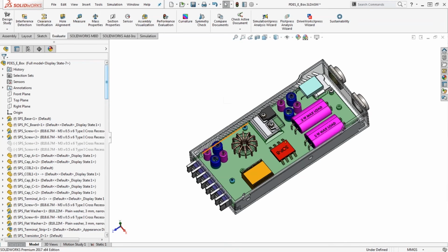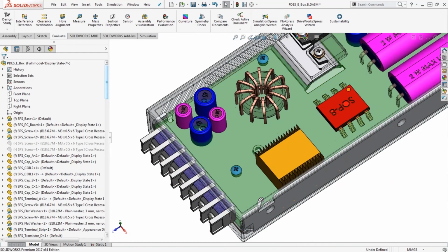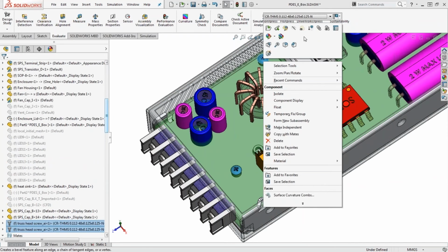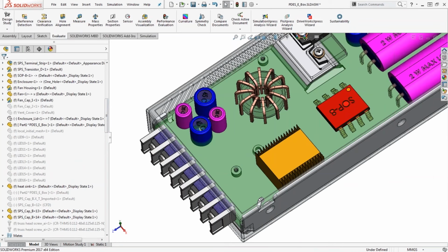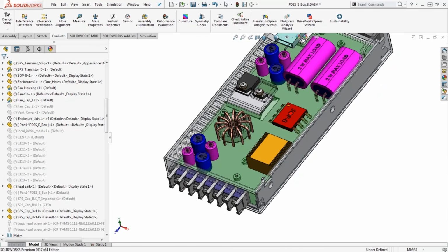So if you're working with toolbox components, have that add-in, then you can turn on that filter to easily select all those components there and then just suppress them. Again, suppressing components that are just not needed. So what happened with these guys? How come these guys are not toolbox? Well, maybe you went into McMaster, you downloaded those part files, and they're just seen as traditional part files. Well, what can you do then?